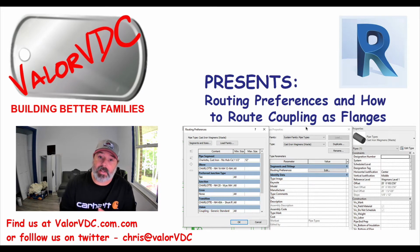And today I'd like to take a few minutes to talk to you about routing preferences, mostly how to route couplings. So if you're running no hub cast iron or groove pipe or weld pipe and you want to illustrate your welds so that you can get proper gapping for fabrication, then you've stopped at the right channel here.